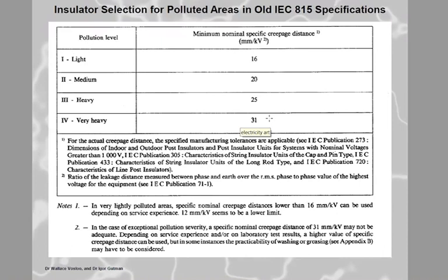Now why do they do that? Because that's not the voltage over the insulator. It can be the worst case scenario in some very unique situation that it would be the voltage. And then the railway guys come along, and now the DC guys come along, and oh my goodness, now we're really confused about what's over the insulator. So what they did is they changed that to unified specific creepage distance, where it is actually the voltage over the insulator, not phase to phase, and so on.